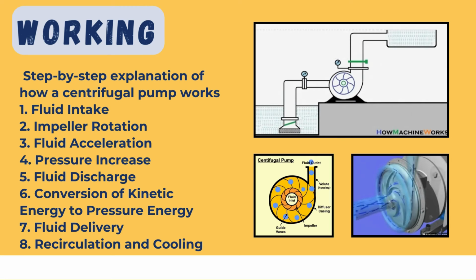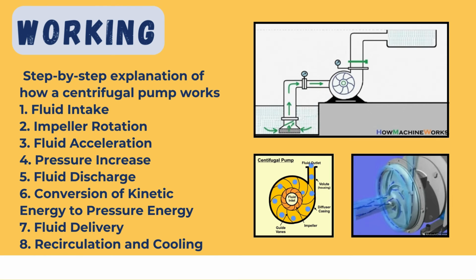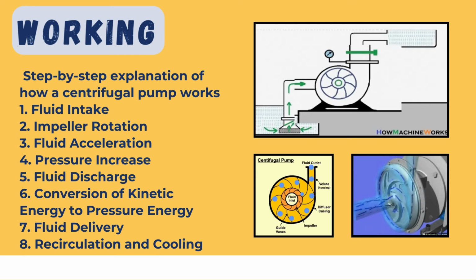So now comes the part of fluid discharge. Guys, the high pressure fluid is discharged from the impeller into the casing or the volute surrounding the impeller. The volute is designed to collect the fluid and guide it towards the discharge outlet of the pump.